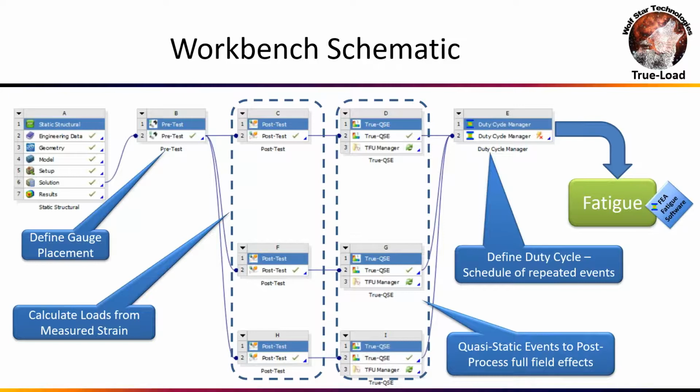And even if you're not using Workbench, the steps are still the same if you're working in the native environment. The nice thing about the Workbench interface is that all of the TrueLoad files are stored inside of the project folder. And so it's kind of a nice bit of housekeeping too, that everything that you need is stored within your Workbench project.